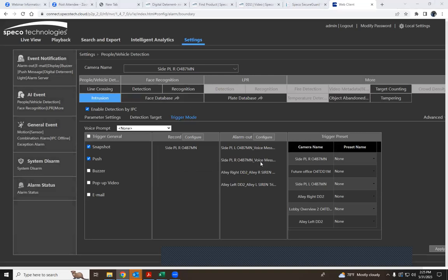So back to the ability to trigger alarms. If I leave it be, you'll see here that now when this event occurs, I'm going to trigger all of these voice messages here. Some other unique aspects: I can also do presets in the system. A good idea is, let's say we have that same warehouse that's got 4 cameras on each side of the buildings, looking at different areas of the parking lots. That's a total of 16 cameras. A really good practice is to put a PTZ on each corner with a pendant mount. We have 4 PTZs.